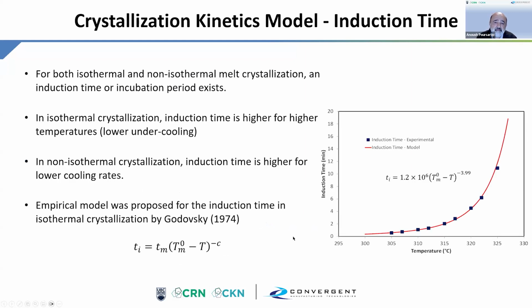What about induction time? The induction time has a behavior where it's higher for higher temperatures. So again, lower undercooling leads to less driving force. And in non-isothermal crystallization, that exhibits itself by having a longer induction time, the lower the cooling rate.